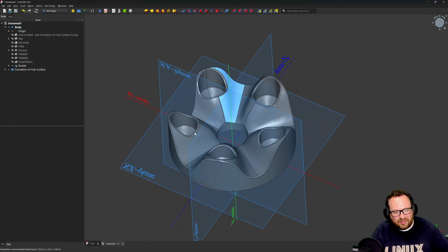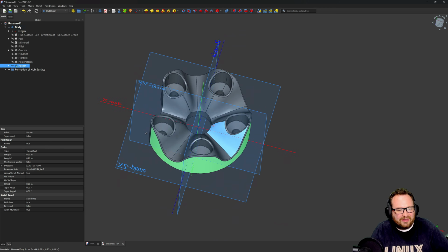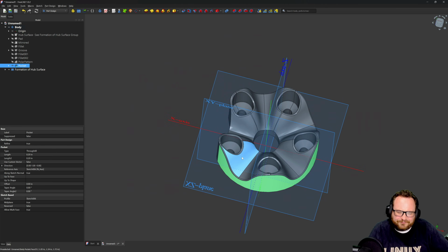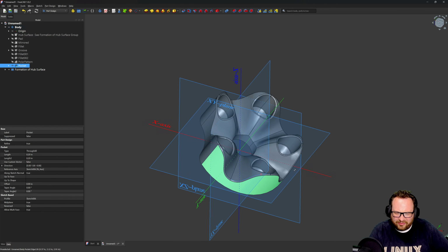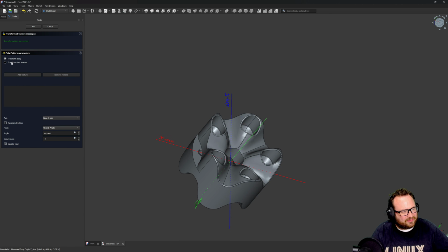Now this is where we're going to watch for zero thickness geometry. This cut ends where the next cut begins in that exact same spot. I feel like Open Cascade, kernel of FreeCAD, is kind of sensitive to those kinds of situations. So we're just going to be cognizant of what's going on there, right? So we choose tool shape, which is going to be our cut right there. Add feature, click on the cut. Yep, there's our pocket. We're going to pattern this around our base Y axis.